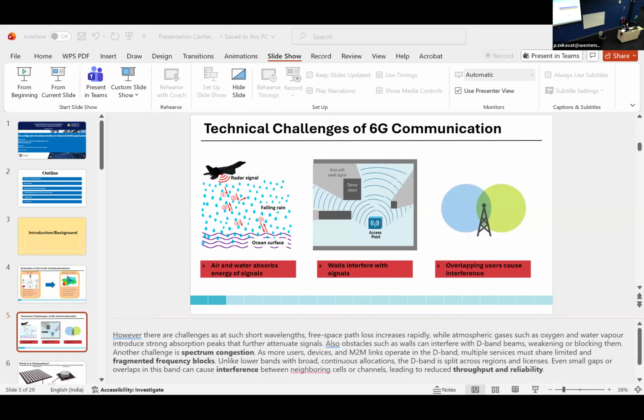So they optimized the geometry, and this achieved a wide 1.2 gigahertz bandwidth, making it suitable for broadband radar and stealth applications. PIN diodes were also integrated into the meta-atom, allowing the resonant frequency to be electrically shifted as well. When the diodes were off, the surface resonated at 5.23 gigahertz, and when the diodes were on, it shifted down to 4.75 gigahertz.